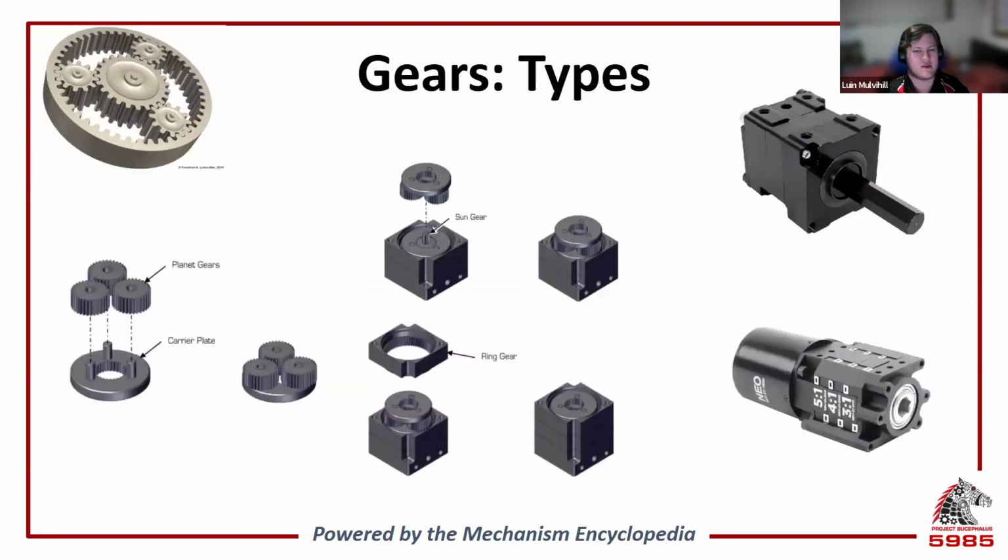As well as spur gears and bevel gears, another gear type that you may hear talked about in FRC is a planetary gear. However, it's actually an arrangement of spur gears. So planetary gearboxes are prevalent in FRC as there are COTS options that allow for customizable reductions in a very compact form factor. Products like the Rev Max Planetary and the Vex Versa Planetary allow you to customize the gear ratio by stacking planetary cartridges together to form a large reduction without the need for large custom gearboxes.